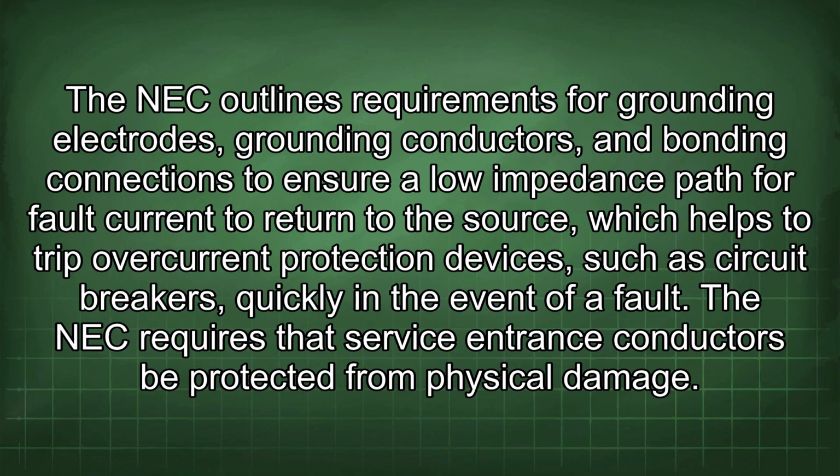The NEC outlines requirements for grounding electrodes, grounding conductors, and bonding connections to ensure a low impedance path for fault current to return to the source, which helps to trip overcurrent protection devices, such as circuit breakers, quickly in the event of a fault.